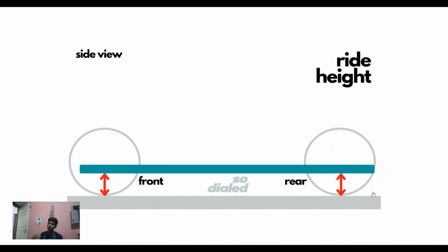When you have a lower chassis height, there is reduced airflow beneath the car, and what this does is create some sort of a ground effect. So when you're moving at high speeds, since there is reduced airflow underneath, that means reduced air pressure, the car is being pushed down. Because of this, there is increased traction on the ground, and the car is able to throttle up very easily. It's able to catch speed very easily. It's able to brake easily because of the ground effect.